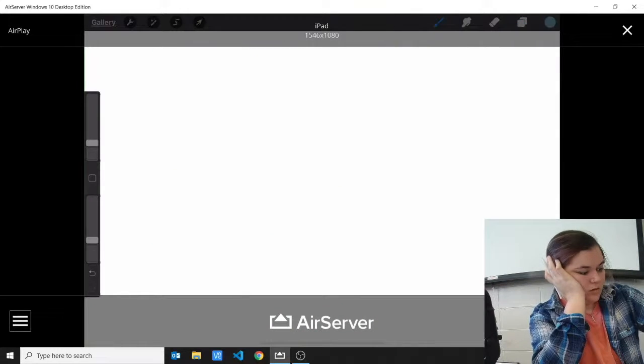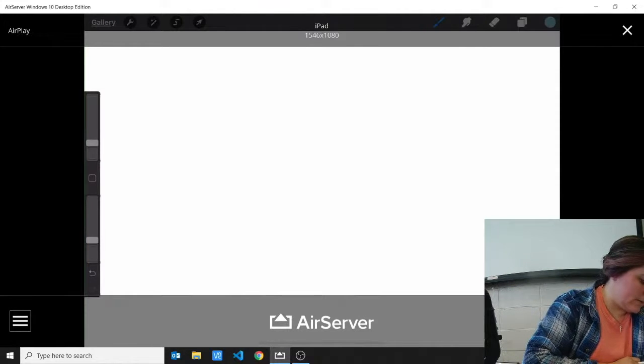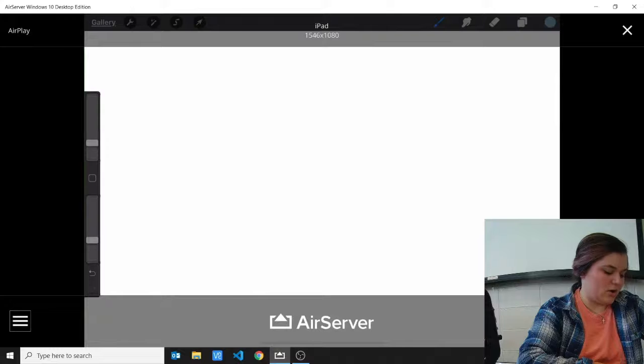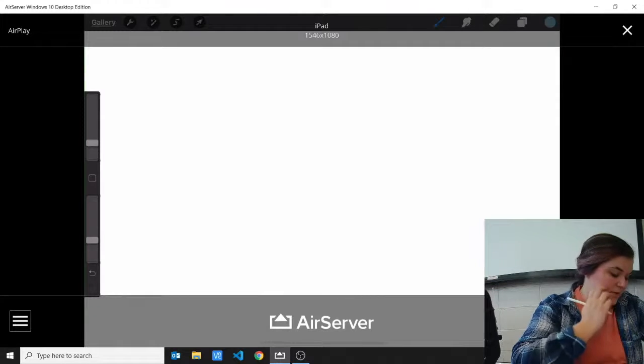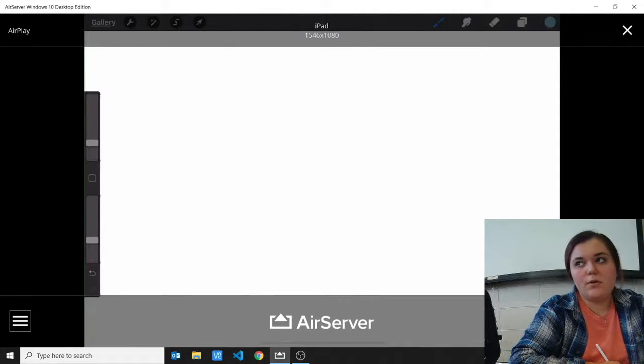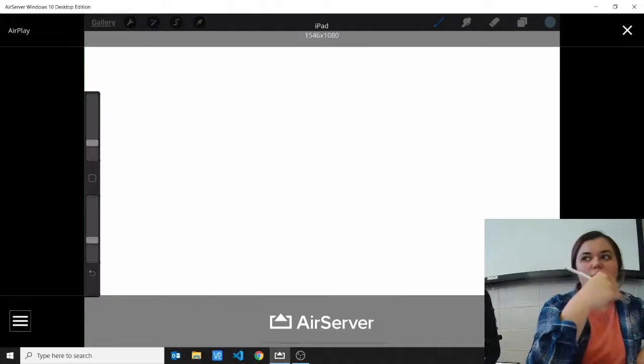So just to go over a few programming rules. Rule 1 would be, and these are basic controller circuit programming rules: the inputs, normally open, normally closed, and special, are placed on the left side of the circuit between the left rail and the output. Outputs are placed on the right side of the circuit, which you know because it's easier to follow. Only one output can be placed on a rung. This means the outputs can be placed in parallel but never in series.